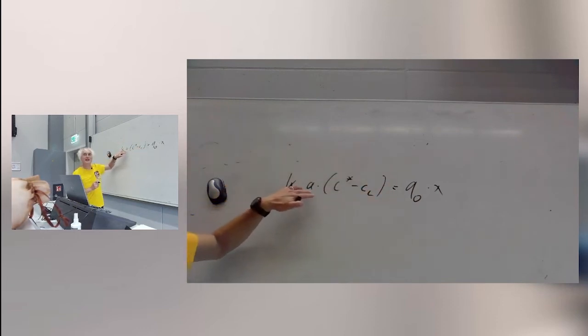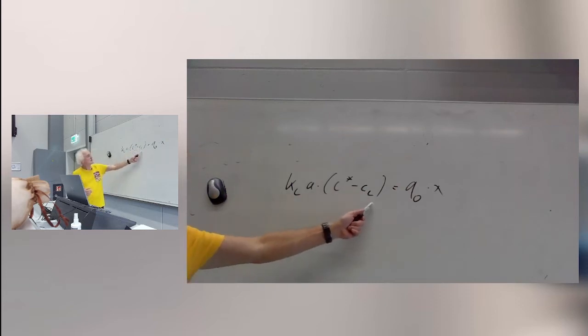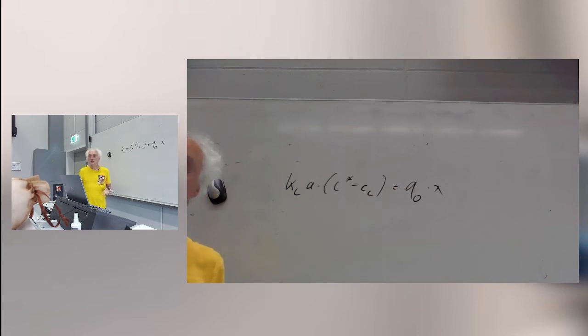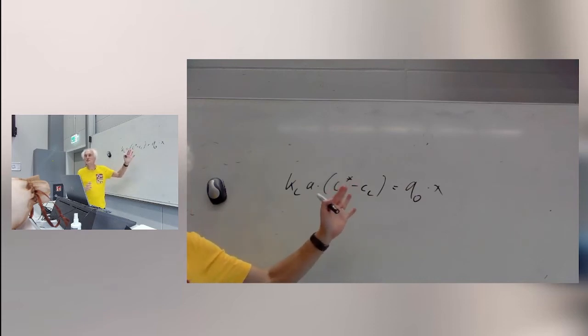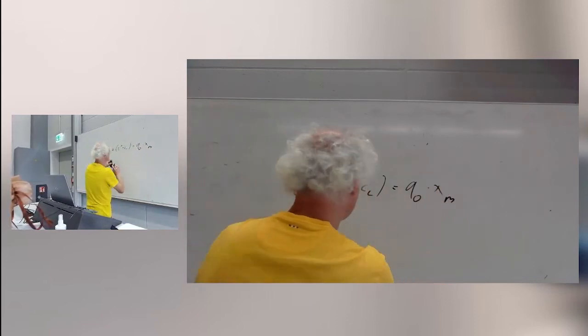Now, the kLa I have determined, I cannot change. The saturation concentration C star I also cannot change, unless I increase the pressure. So I have it given at a certain temperature. But the minimal C_L is 0. Of course, q_O2 is then greater, but 10% of 0 is also almost 0. So we can say, I'll write this on a different line,